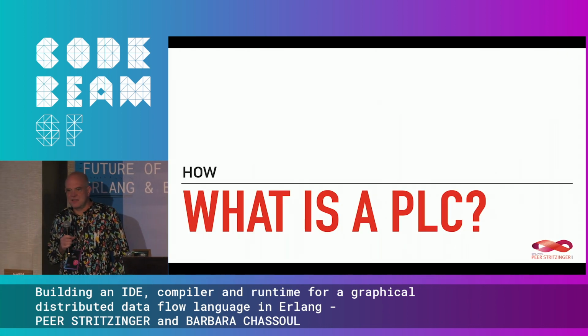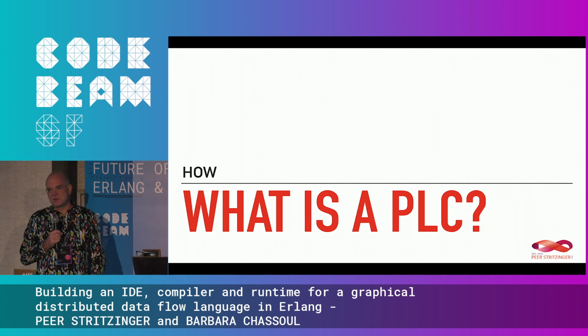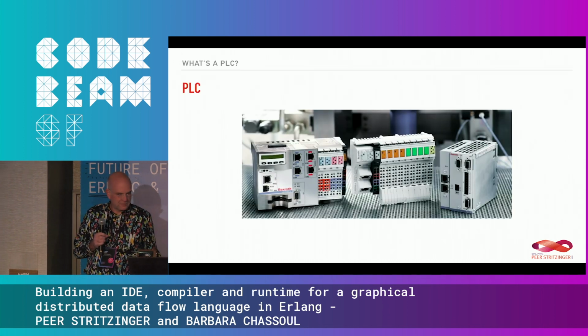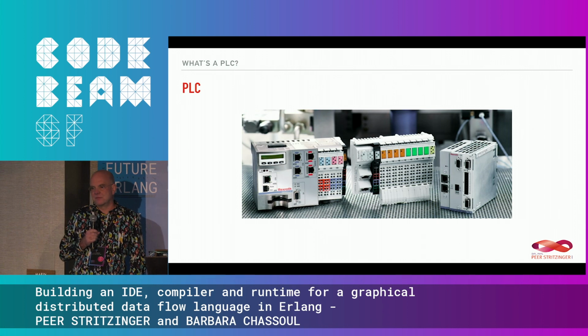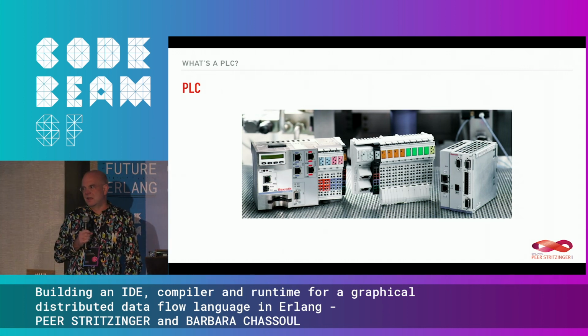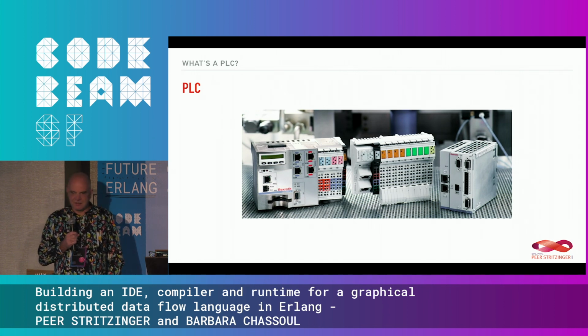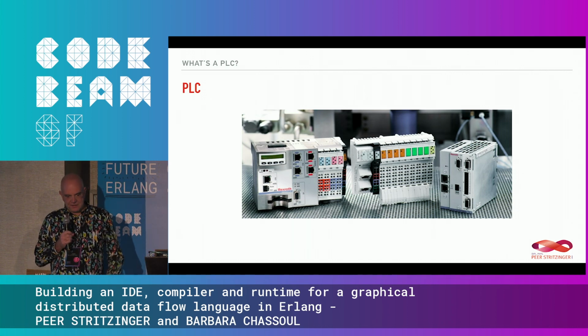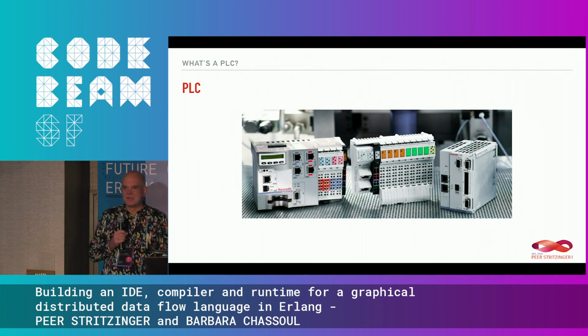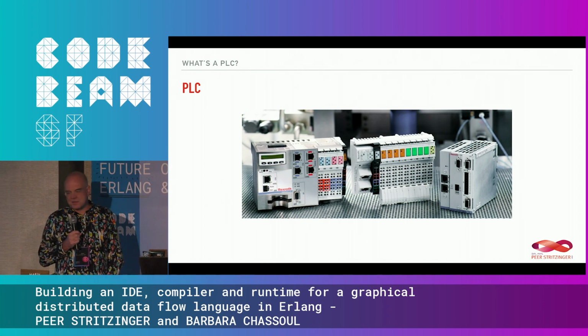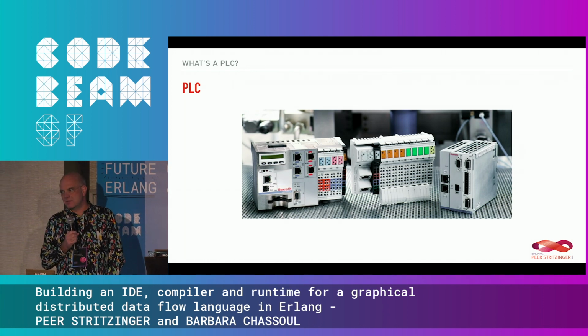So what is a PLC, or programmable logic controller? It's the computers that make everything run, like your garage door opener. Yeah, maybe that's a ready-made box, but a custom-made garage door opener is usually driven with a PLC. There are a few form factors of PLCs. You have on one side a little box with a PC in, or with some kind of embedded controller in. And then the field side is basically wiring for I/O, usually 24 volts. So this is for industry. It's the computers that make industry run, also. Factories run on PLCs, basically.